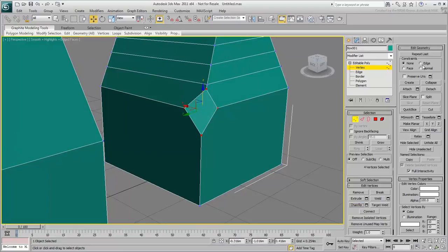When moving vertices, you can constrain them to edges to force them to slide along any edge to which they are connected, like a bead on a string. Just remember to turn off the option as soon as you've finished with it, or it may cause problems later.